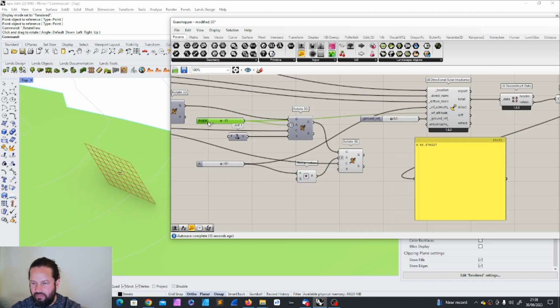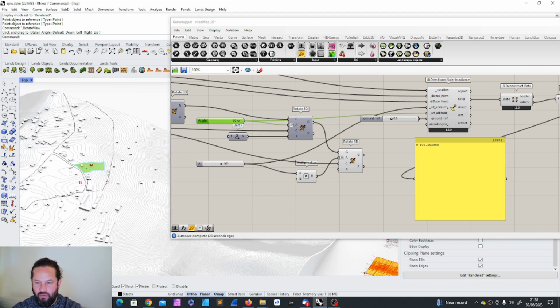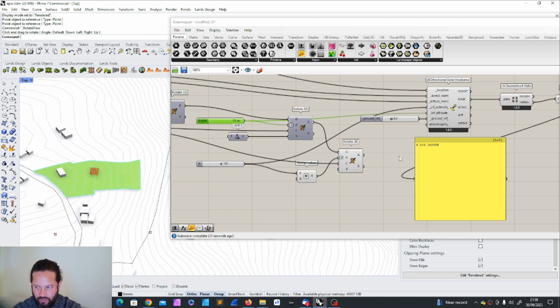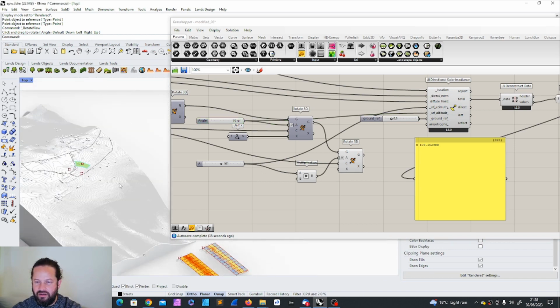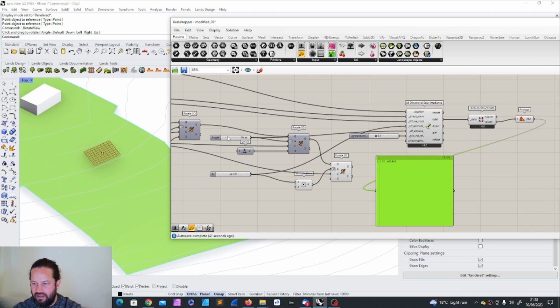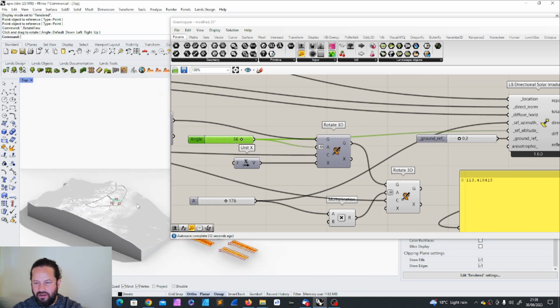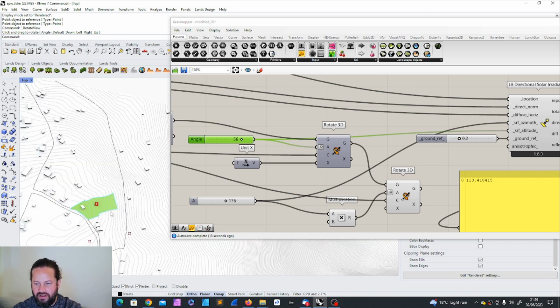So we can play with this. I know that because I'm using the weather data from Norway, from Oslo. That means in the south, the panel needs to be orientated to the south in order to get more. That's why I know that I don't need this multiplication by -1. So I don't need to reverse the angle, because now I can see that if I play with these values here and this, then I can try to optimize. I think this is like 130. I know that this was one of the values I got before with this weather data.